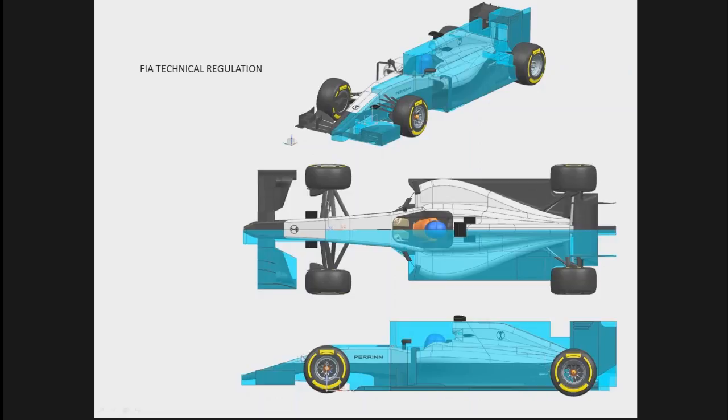One of the problems we have this year is, again, I will use this picture. The nose has to be under this line, and it needs to have a minimum thickness by regulation, and also because you need to go to the crash test, so you cannot afford to have a very thin nose. So you can imagine that the underside of the nose is very close. You can see it here. The distance between the nose and the FIA section under it is quite small. This is actually a problem because, and you've got the pillars as well.